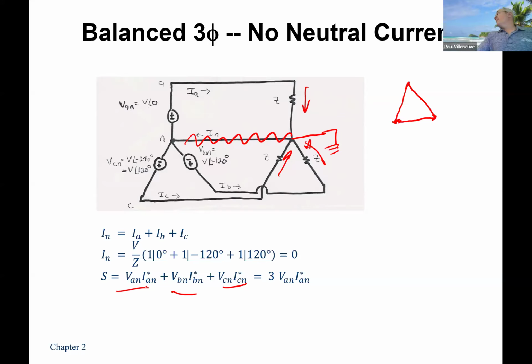So we've talked about it a couple of times, and we even saw it when we were looking at our bus example. We oftentimes work off what's called a single line diagram because one of the phases matches the other two. They're all the same except for the phase shift. So why bother drawing 3 phases if you're going to get the same results? So we use single phase analysis. But this only works if the neutral is at 0 volts.